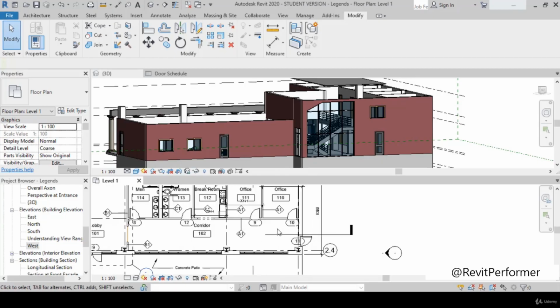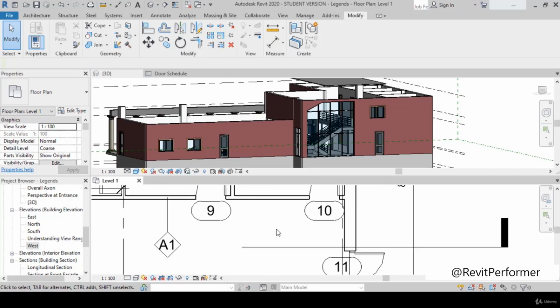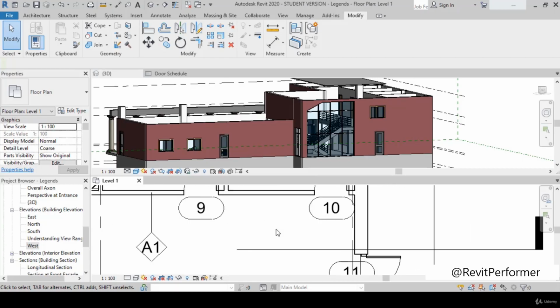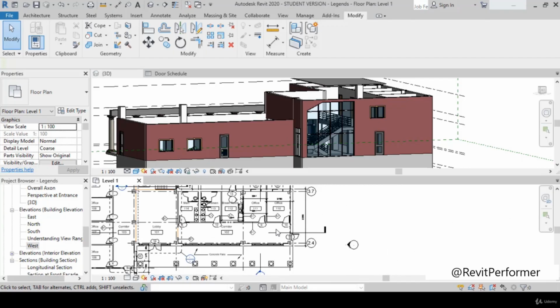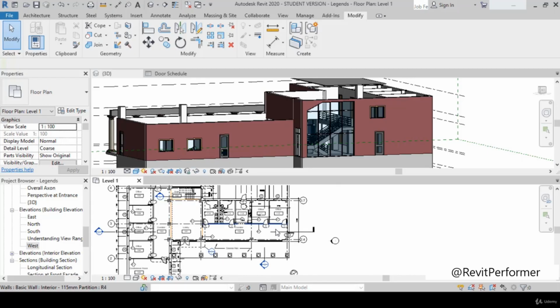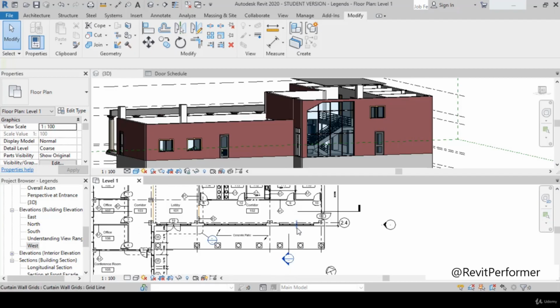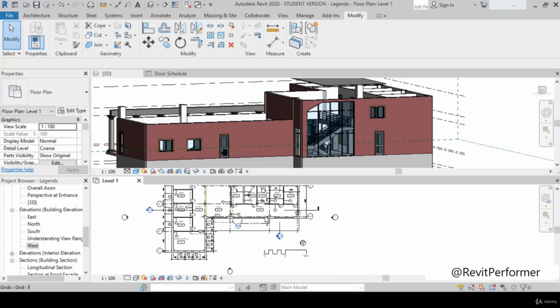When you scroll anti-clockwise, it will zoom in, and when you scroll clockwise, it will zoom out. That is one function. Or you can take the zoom command, go to the rectangle command and click it. This is also zoom. So this is the function of the zoom command.